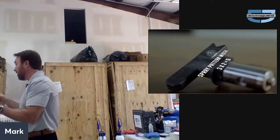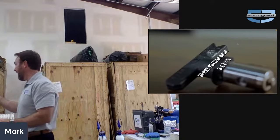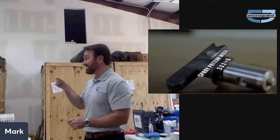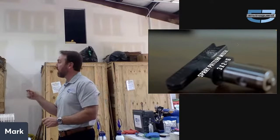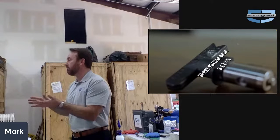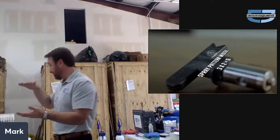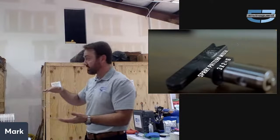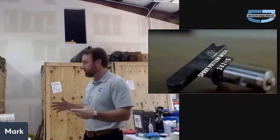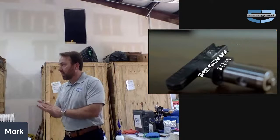This is going to blow you away, because we were talking about like 10 wet mils and things like that. In a lot of those coatings, we're going to be applying those at 30 to 60 wet mils. And those are going to be products that are 80+% solids content. They're almost pure solids. So your viscosity, everything is measured in centipoise. Like MaxGuard might be around 10,000 centipoise. These are going to be like 50,000 centipoise, like 5 times the thickness. So we won't be able to use systems from Lowe's and Home Depot for their application. It'll require a truly professional rig to apply those coatings.